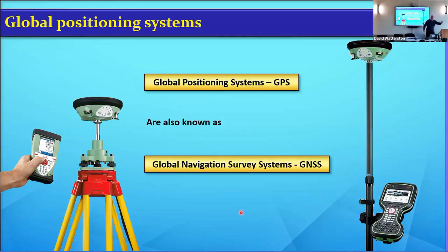So at the other end, it was meant to flow down, but it doesn't, it's flat, right? So they end up building it up so that it flows, but then that's below where it's now going to go out because there were errors further down the line. So they can't do it by gravity anymore. They've got to put in a pumping station. So they put in a big massive hole in the ground, a collection unit, that takes all the sewage, and then when it gets up to a level, it pumps it back out to where it was meant to go with gravity. And you can imagine it's a huge expense.